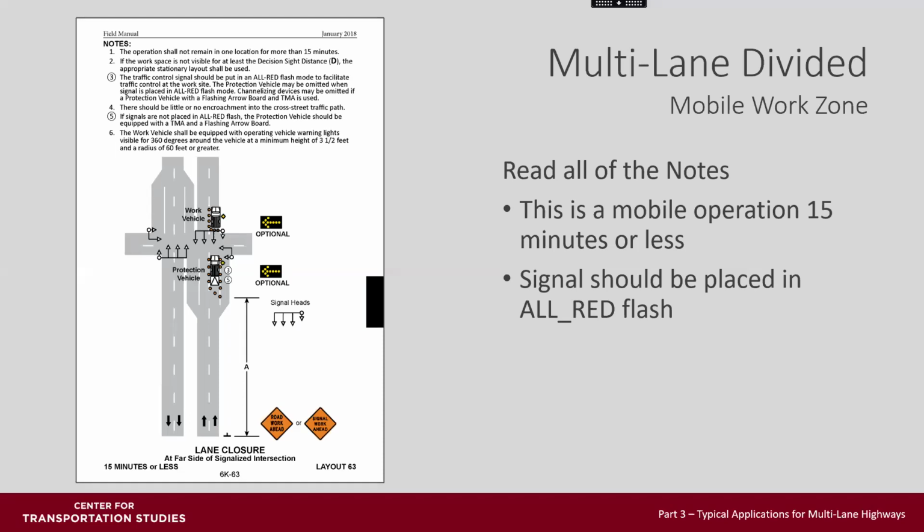This is a very specialized workspace, primarily for working on traffic signals. Please note the 15-minute time limit and the recommendation to place the signal in all red flash. Again, when changing signal operations, make sure you have authorization from the local road authority.